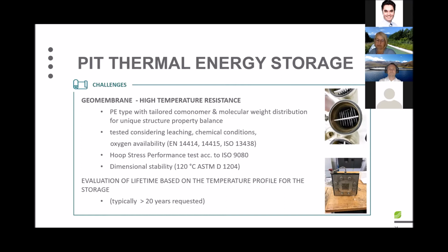chemical conditions. For geomembrane applications, we must not forget about dimensional stability. We always have to evaluate this, because it is a key performance factor in these applications, as we want the utmost laying flat. What you can see in the pictures here are typical autoclave procedures. One is from Denmark, which has air insertion on one side and water insertion on the other side. The other one is insertion in the fluid at higher temperatures and higher pressure.